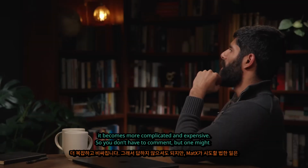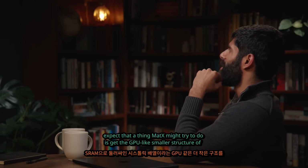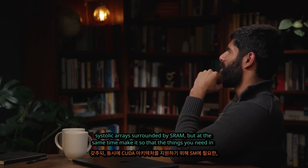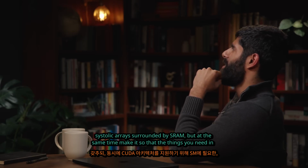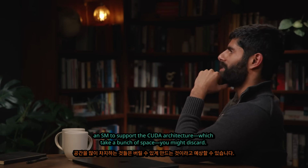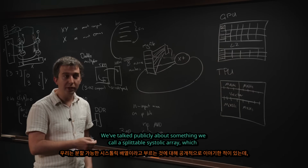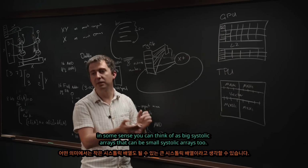You don't have to comment, but one might expect that a thing MatX might try to do is get the GPU-like smaller structure of systolic arrays surrounded by SRAM, while also discarding the things you need in an SM to support the CUDA architecture that take up a bunch of space. We've talked publicly about something we call a splittable systolic array, which you can think of as big systolic arrays that can be small systolic arrays as well.